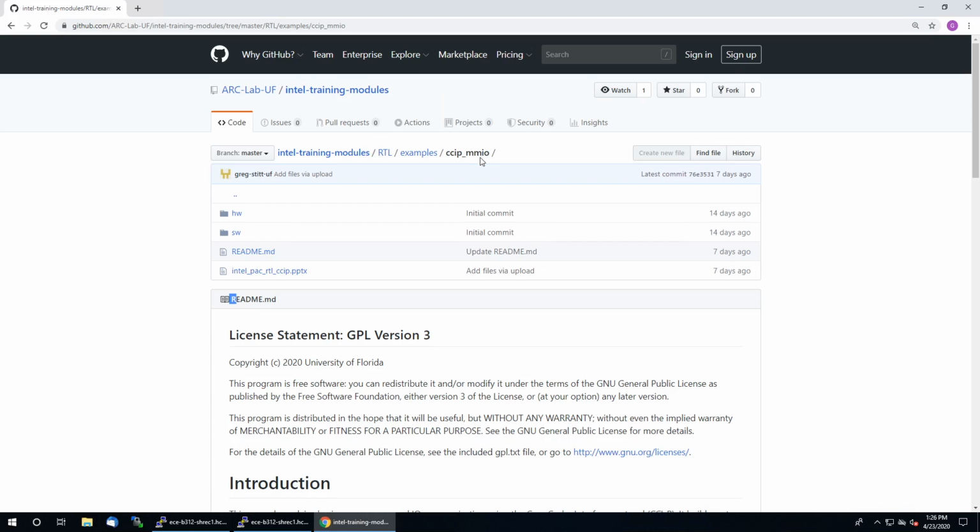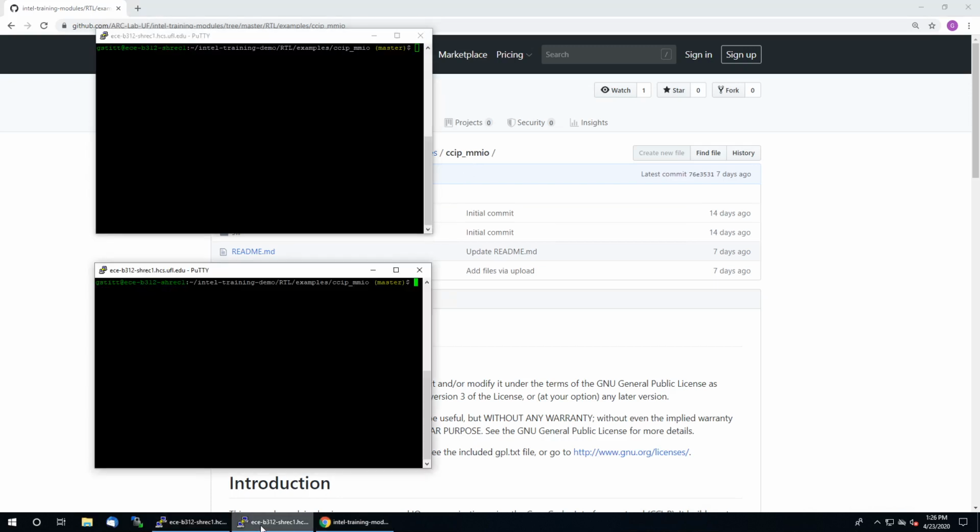All right, so Intel ASE is a very powerful tool because it basically lets you do hardware-software co-simulation. So it gives you a simulation environment where you can simulate your RTL code for the AFU while communicating with software running on the processor. Now, that's a very powerful testing and debugging environment. All right, so how does this work?